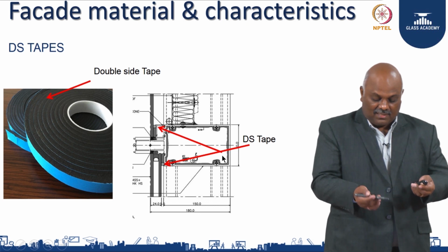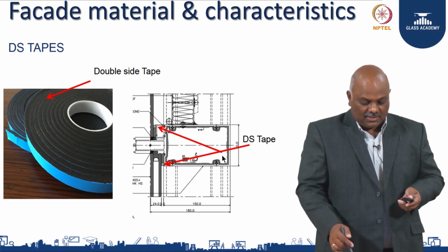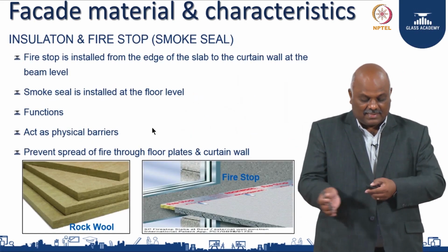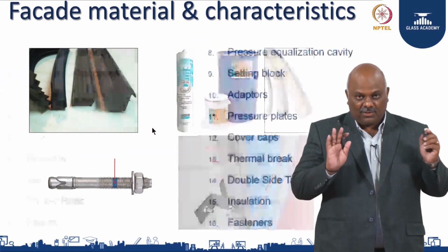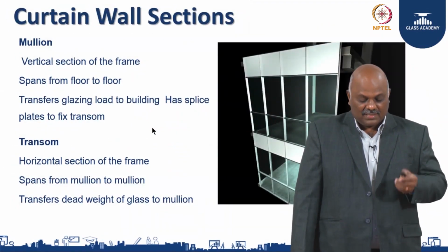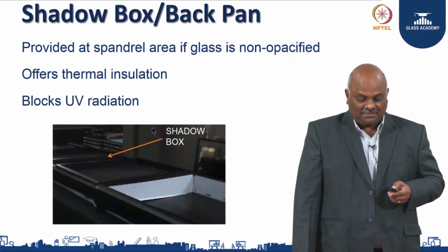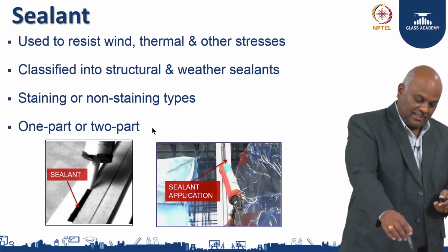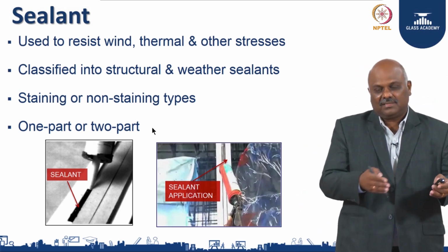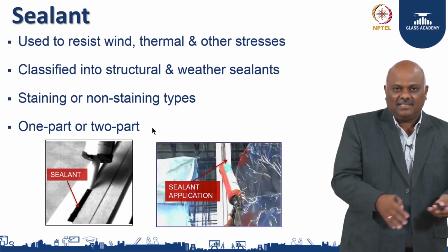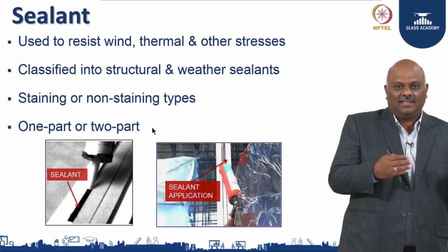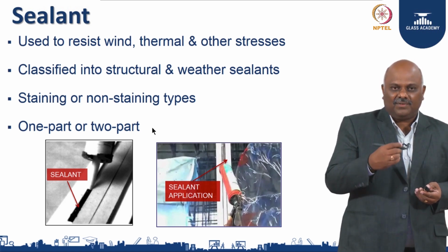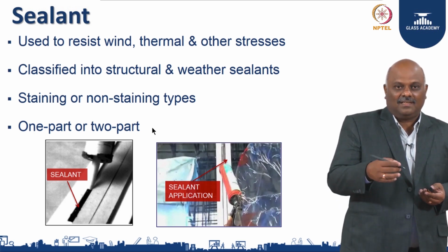It means a normal metal to metal, there will be a small gap where you can use weather sealant to seal. So, structural sealant holds a structure against a structure, like in the mullion or transom, wherever you want to glue the glass to, which holds them together. Again, you have different materials you see here, and I am just going through very briefly, because all this material in specific will be taken care of by other colleagues of ours, who will give you complete detail about each product.